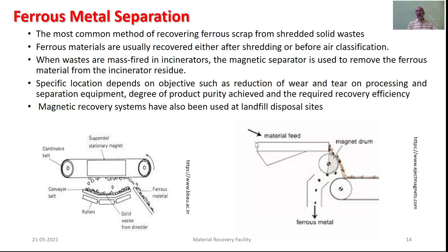The material could be fed over the conveyors, passing over a certain magnetic drum. In turn, as it moves, it will be adhering to these magnetic drums. The remnant residue will be passing over the next conveyor, whereas as the magnetic material loses the magnetic area, it would get separated out of the process.